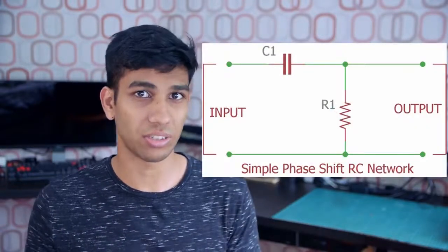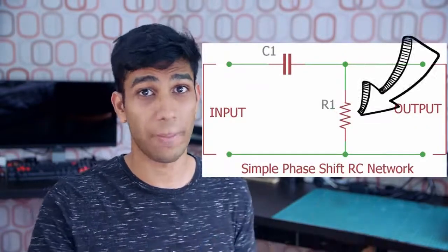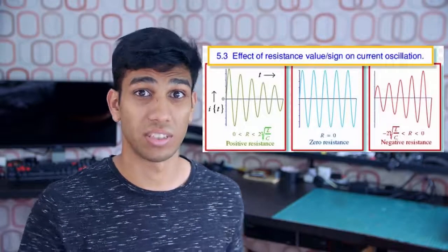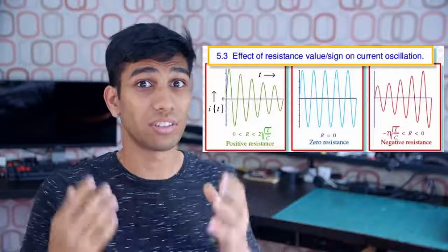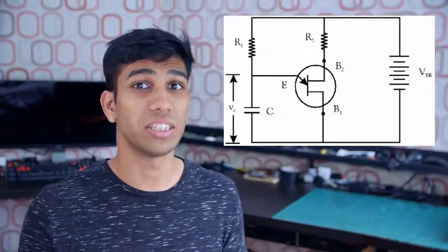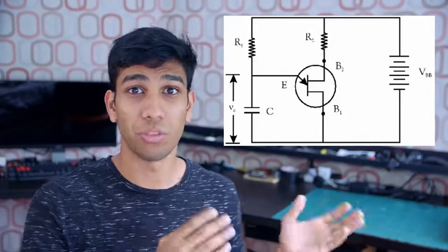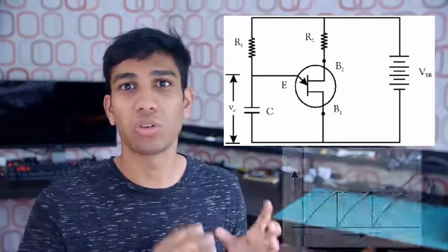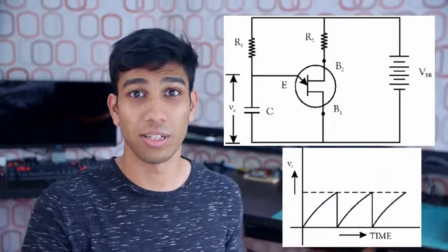Next, we have the RC oscillators that are created using resistors and capacitors, and these oscillators, unlike LC oscillators, create low frequency waves. These oscillators are often called audio frequency oscillators due to their ability to generate audio frequency signals. Next, we have the negative resistance oscillators that use the negative resistance characteristics of its electronics devices, such as tunnel devices. We also have the UJT relaxation oscillators that use both capacitors and resistors to create those sawtooth waveforms that we were talking about earlier.